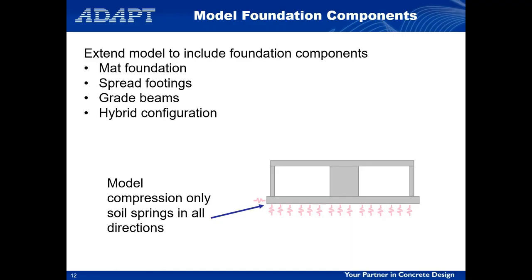So you're kind of stuck with this challenge: even if I'm using another finite element program to do the PT design, now I've got to take all of those forces, the hyperstatic forces, the redistributed dead loads, live loads, and bring all of those back through the columns and foundations.